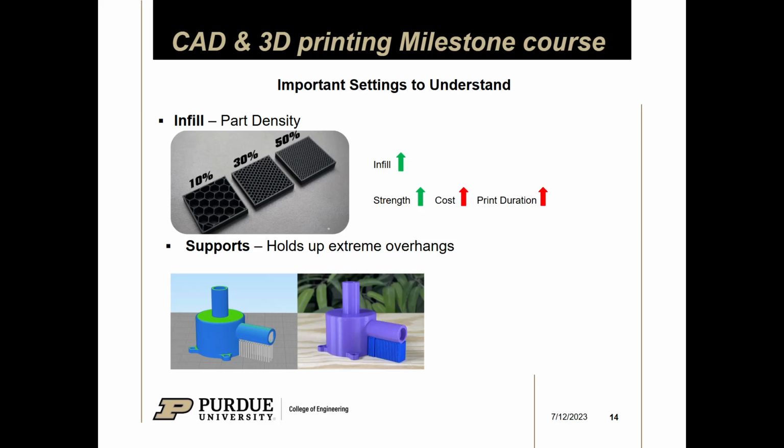Hopefully those parts are going to be making their way around the classroom. But yeah, you can see that all these prints are hollow on the inside, and it's mostly just to save on print time, but also most of the parts that you make don't need to be completely solid. A lot of the strength will come from the outside, and the inside won't really be doing much. So oftentimes it's good to run a lower infill.